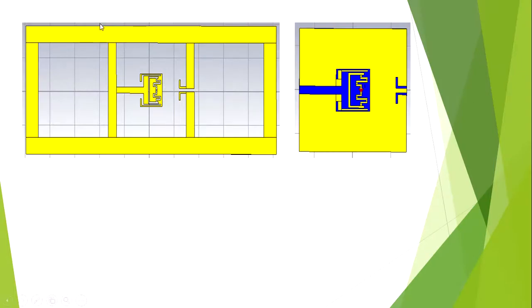So this is the inlay. Before we fabricate it, we would like to design this inlay in CST Microwave Studio, so that in the fabrication process we can print this pattern onto the substrate, so that the unwanted part can be etched away, and the desired copper part can be obtained in such a pattern. So this is the RFID tag antenna structure for my design.